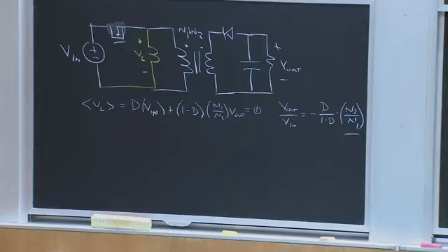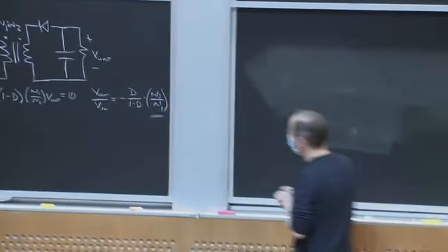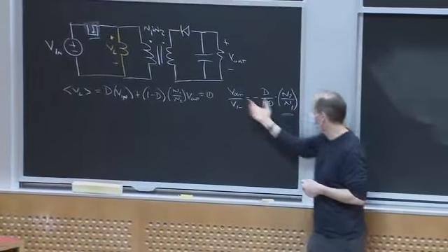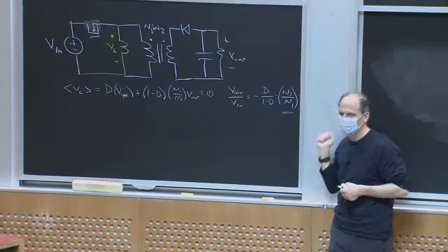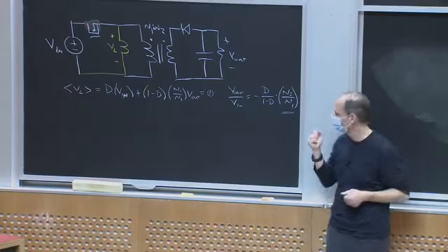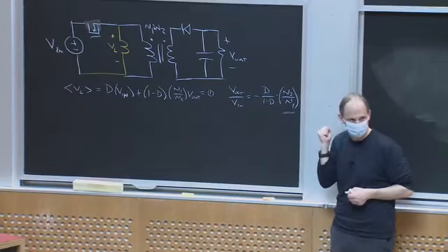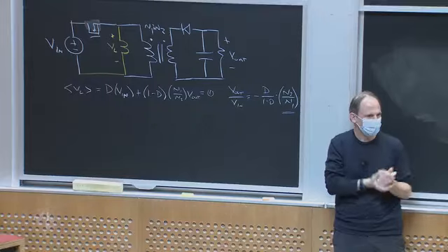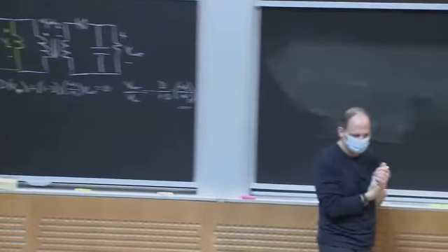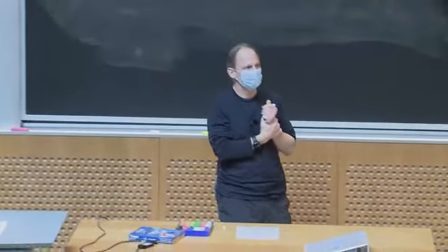And that'll let me get a certain voltage conversion ratio. It gives me an extra way I can scale the output voltage compared to the input voltage. A fixed scaling is set by the turns ratio, but nonetheless it lets me pick my duty ratios the way I want. Okay? Any questions about that, rescaling?